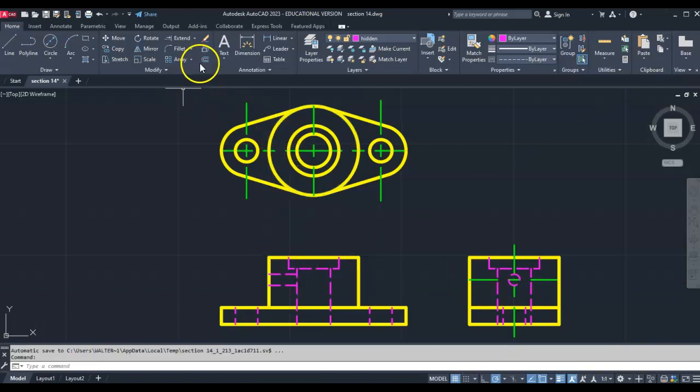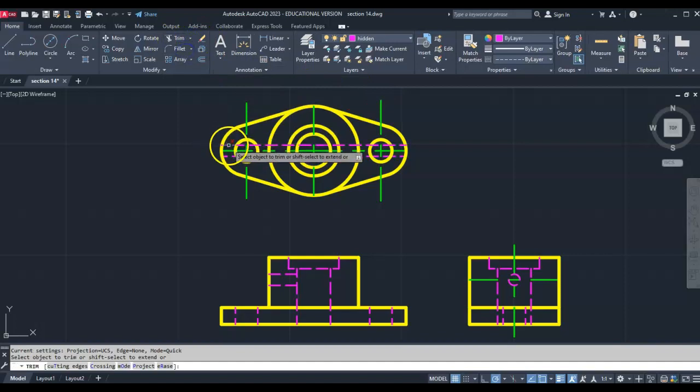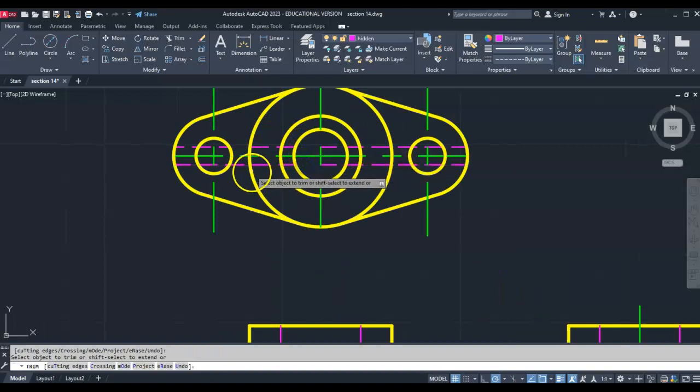And then up here, I can either copy this up, or if I do offset, if it's 1/4, I'll do offset of 1/8. Center line up, center line down. Those two will be hidden. And then I can trim. Just trim the parts here. I can delete the rest. Save me some clicking. Delete.